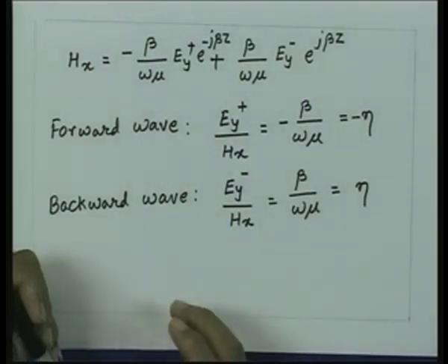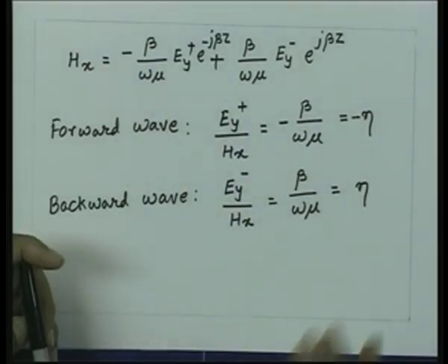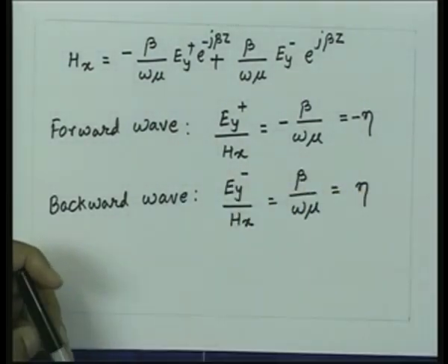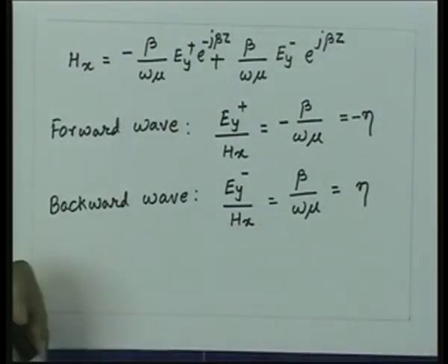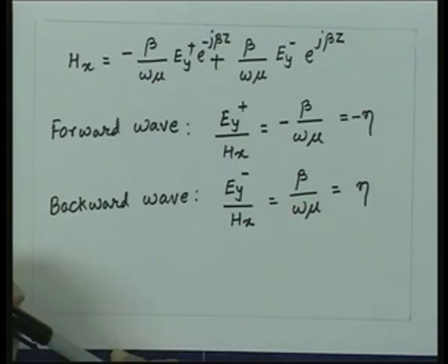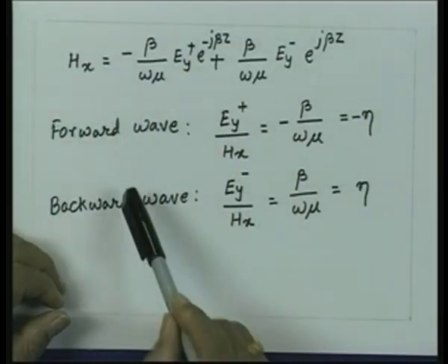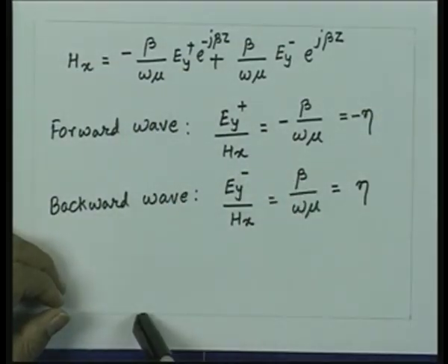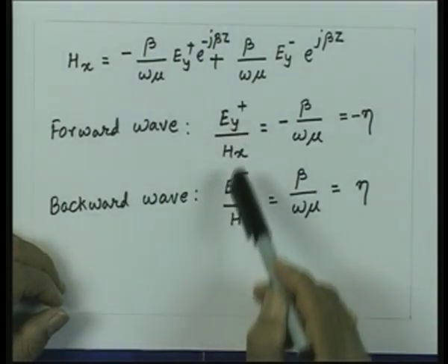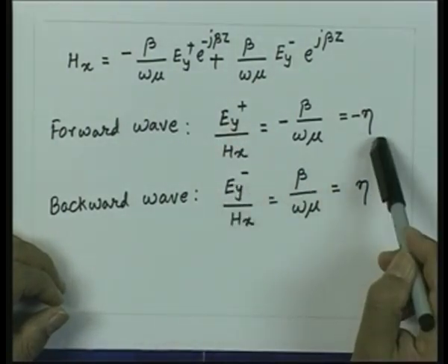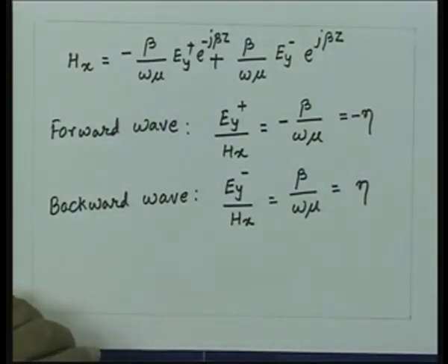So, essentially what we have now is E, H and the direction of propagation, and if you consider this as a sequence and follow the right handed system, if I have the E to H in the right sequence, so I have Ex and Hy, the ratio of this electric and magnetic field is equal to the positive intrinsic impedance.